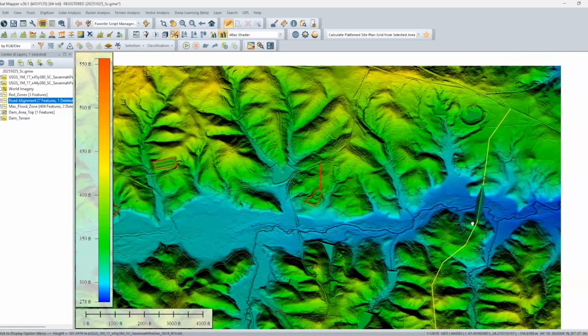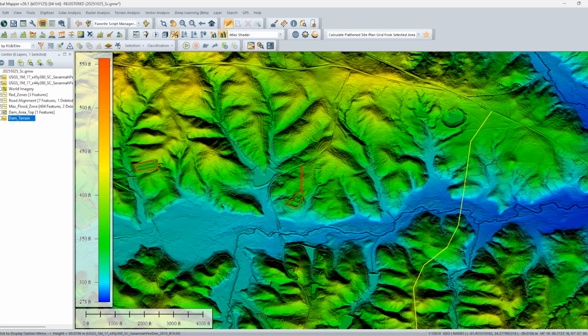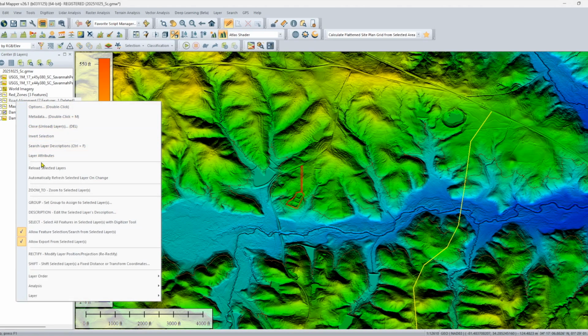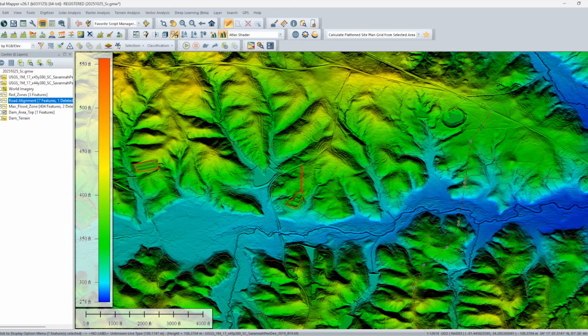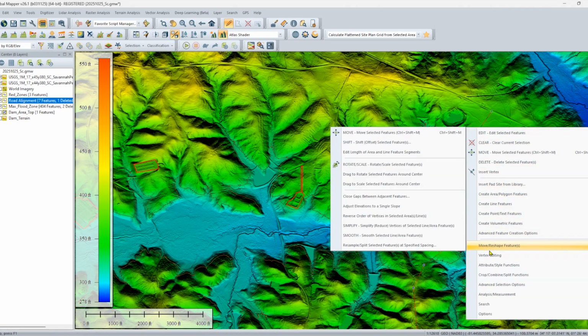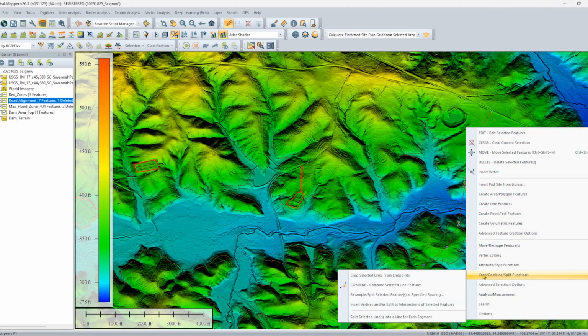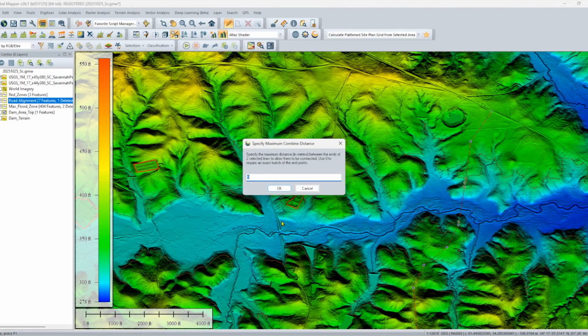Now we're going to look at how the dam changes the site profile. To do that, I'll cut a cross section along the road alignment. But remember, earlier we split that line while setting up the dam center line. So before we run the profile, I need to merge those segments back together into one continuous alignment. That way, the software reads it as a single path across the entire site. Once that's done, I'll open the Path Profile tool.